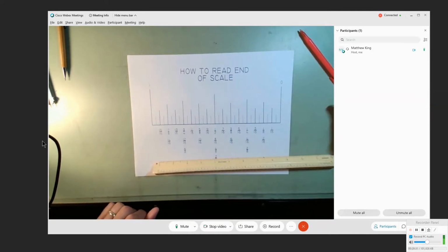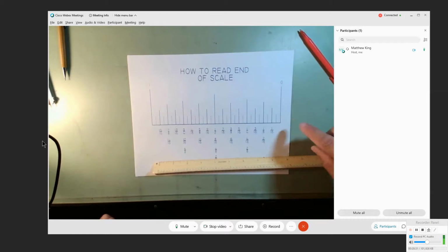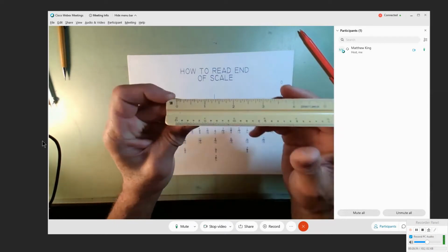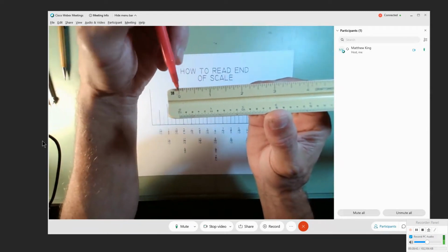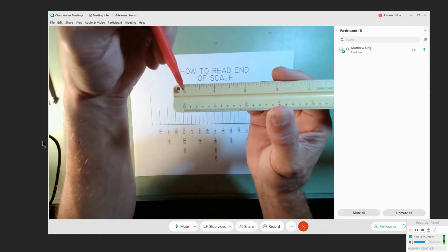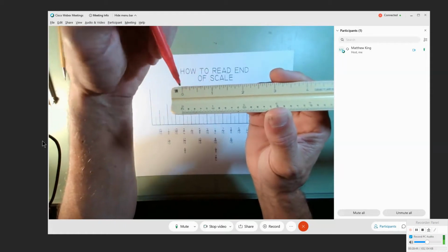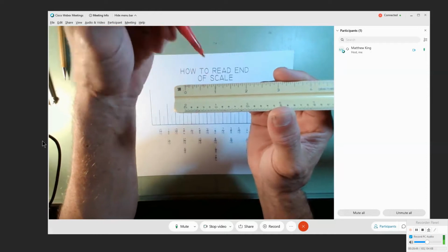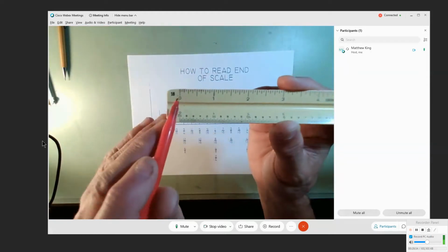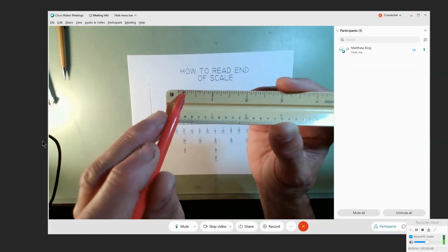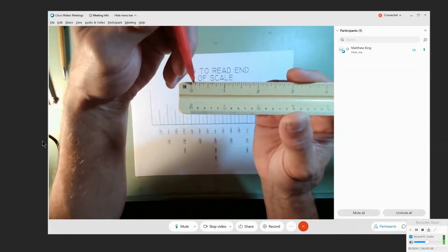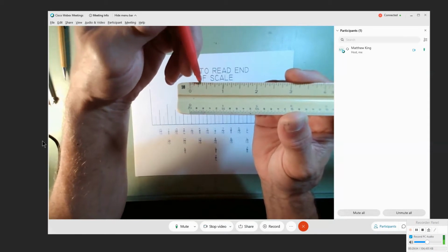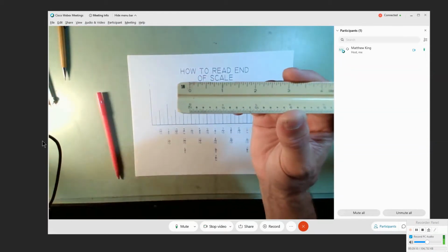So where this can be dangerous is if I said to you, I want you to count and find me 3/16, right? Because on this scale, this scale that says 16, this is a full inch, a real world inch. If the weatherman said we're going to get an inch of rain, that's how much we would get, between 0 and 1. This is just divided into 16 equal parts over that 1 inch. And you'll notice that these little lines or graduations are at different lengths. And the super tiniest ones are at a 16th. So anytime you land on one of those really small ones, it's going to be something to the 16th.